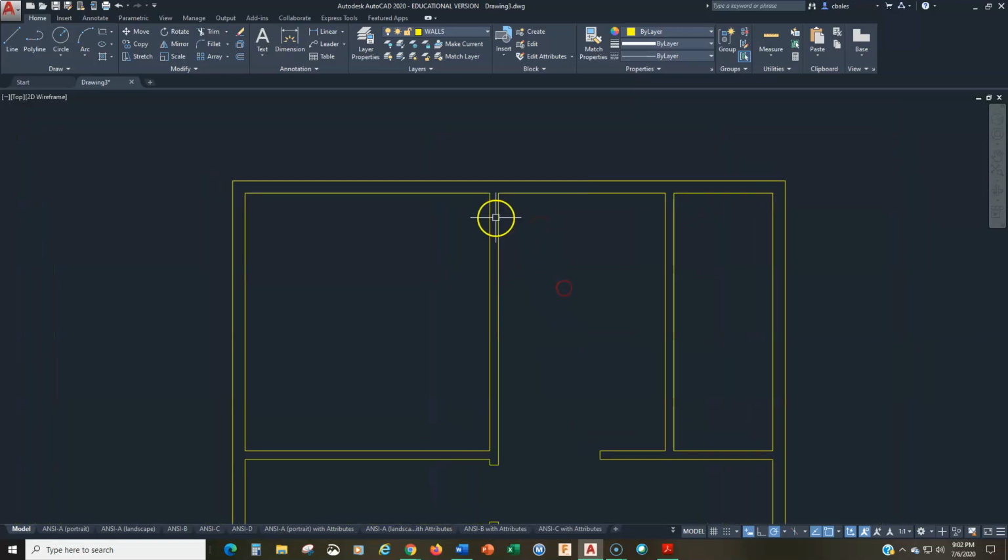All right, so now let's finish the closet over here. So this is the first bedroom. The closet is 5 foot 1 inch wide. So we're going to go to offset 5 foot 1, and we'll take it from there, and we'll go in like this. And the interior wall is 4.5 inches.